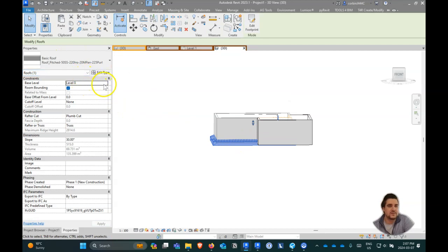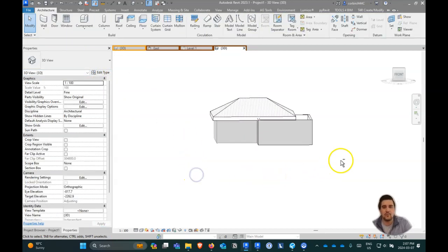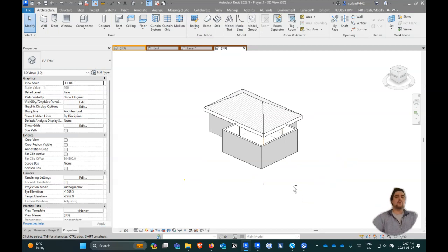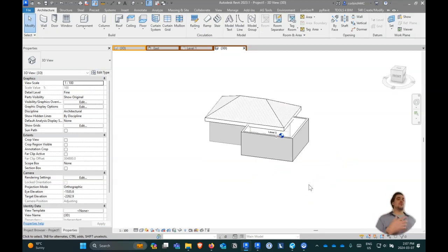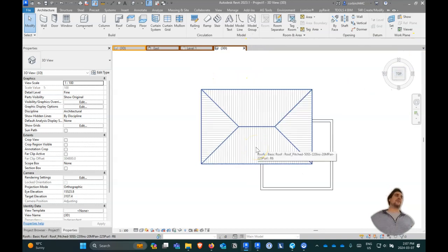We have this kind of complex roof at level 1, and we want to join a new roof in. So the first step I would go about doing this is modeling the new roof. I think that's the first thing that we want to do. We want to figure out what that new roof is. And we take that same kind of layering approach with our roofs and floor systems as well. So we'll often model sheathing and exterior material, like sheathing and shingles, but we don't model the structure as part of a roof assembly. And part of that just gives us a lot of control over the layering.